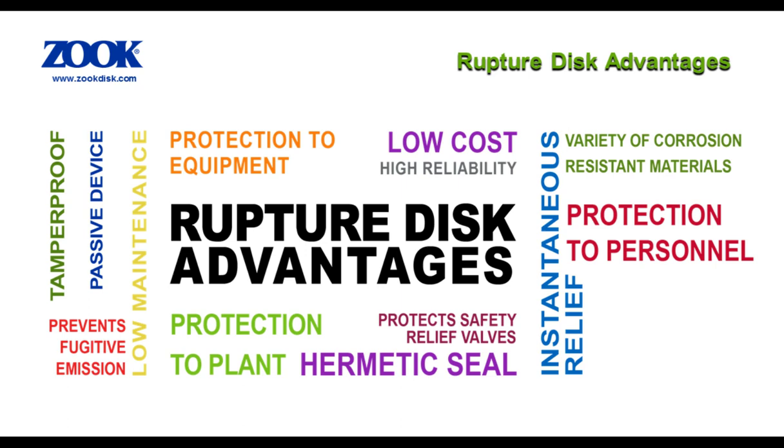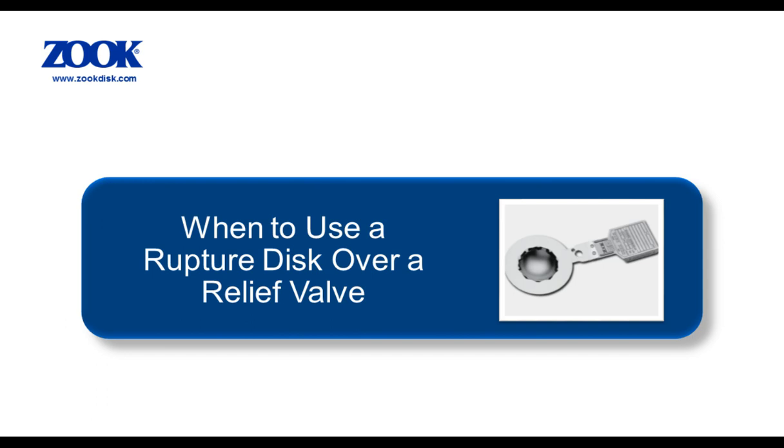Rupture disks are passive devices with no moving parts. Rupture disks provide leak-tight seals and are available in a wide variety of corrosion-resistant materials. Rupture disks are low-maintenance devices with very high reliability. They are a time-tested, tried-and-true safety product. Rupture disks are extremely fast-acting, typically going from closed to fully open in less than 3 milliseconds. Rupture disks are a very effective, low-cost solution to a pressure relief requirement.